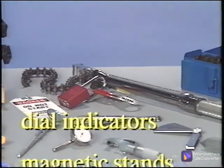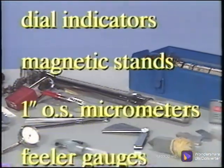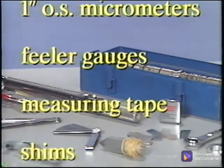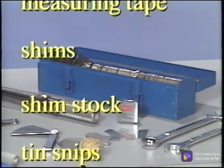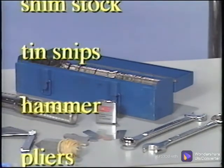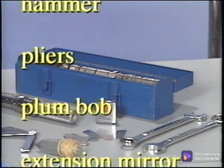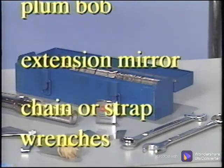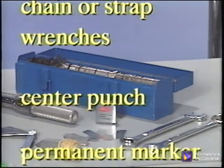Get the dial or digital indicators, magnetic stands, a good 1-inch outside micrometer with at least a 1 mil resolution, feeler gauges 3.5-inch and 6-inch long, measuring tape, pre-cut stainless steel shims of appropriate size, brass or stainless steel shim stock, tin snips, small hammer, needle nose pliers, a plumb bob, an extension mirror, chain or strap wrenches, automatic center punch, and a permanent marker.